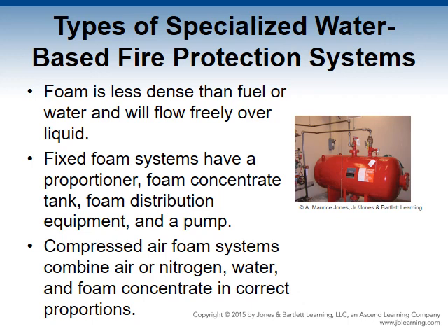It can either use a Venturi proportioner, a pressure proportioner, or a balanced pressure proportioner, and that's just a way to add air to the solution to get the bubbles. You have a foam concentrate tank. To avoid corrosion, it must be made of materials that are compatible with the foam concentrate or have a bladder that is compatible. The tank size depends on the amount of concentrate necessary to protect the hazards for the minimum required duration. Then you have the foam generating distribution equipment.